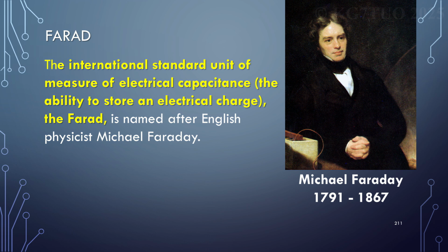I believe this one's turned on as well. When I shake it, you can see the light come on, right? Every time it goes through there, it generates an electrical current because that magnetic field is crossing all those conductors. Turn the switch off, do this. It's got a capacitor in there that will store the power. Same thing over here for a while. These are not high-tech, super duper capacitors that are going to hold it for a month. But if you go camping and you have one of these, you don't have to buy batteries until this cheap plastic handle breaks. You watch for these on sale, $2 a piece, you take 6 of them. So that's Faraday's principle and how it works.